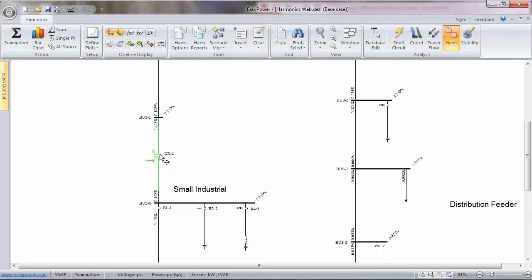So what type of heating am I seeing on my transformer? Now, you don't have to click it. I did that just to highlight that we're going to look at the derating here. Once you've run a summation calculation, all you have to do is press transformer derating. That's this button here. And here it shows you the transformer C57-110 derating. What that says is I can't load that transformer past 89.9%, and if I do, it's going to begin overheating. Overheating means loss of life, insulation damage, etc.